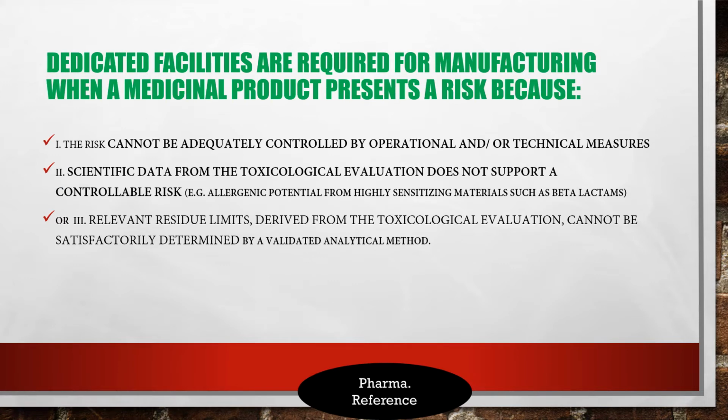Dedicated facilities are required for manufacturing when a medicinal product presents a risk because the risk cannot be adequately controlled by operational and/or technical measures, scientific data from the toxicological evaluation does not support a controllable risk, e.g., allergenic potential from highly sensitizing materials such as beta-lactams, or relevant residual limits derived from the toxicological evaluation cannot be satisfactorily determined by a validated analytical method.